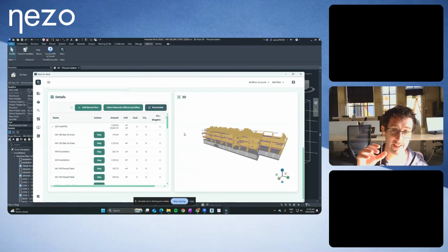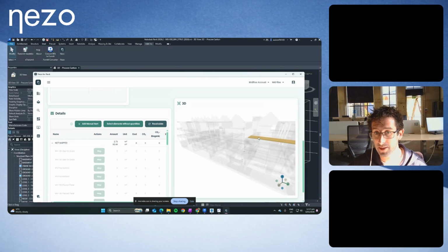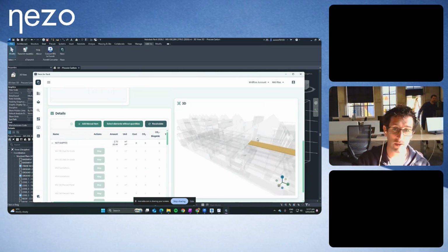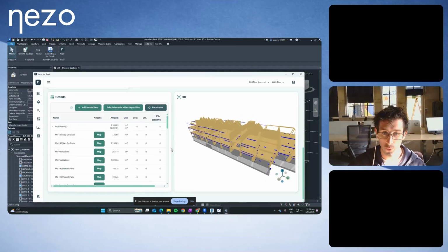We want to run the calculation here too and bring the quantity information from your model, from your design, together with the data to get results. We've already identified we can do it earlier with low levels of detail because we can use those mid-rise assemblies. For instance, this model, perfect example, has CLT floors. We don't need to model any of that floating floor. We can just apply that material that includes the floating floor and get that result. Lower amounts of geometry, earlier results.